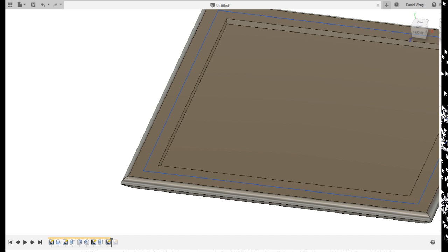Yes? Are you not able to, like what you had before, just drag it? Yes, we can, but I'm going to try and do it this way, to show you reference geometry, given that I have been put in this scenario. But yes, you can move it by right-clicking and then just moving it. What we're going to do is construct an offset plane, and I'm going to shift that back 20 millimeters.